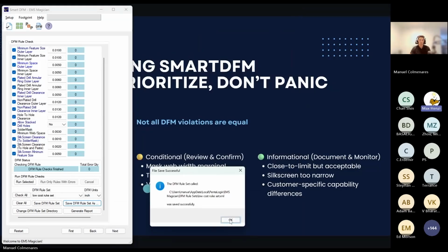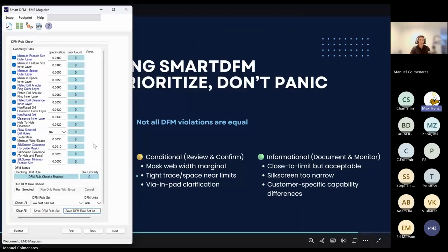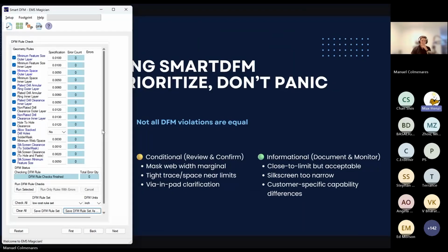And it doesn't have to necessarily align with a particular PCB manufacturer. You can just set up different rule sets for different technology types of boards and then run them through there. And so if you know that, hey, this board shop that I like over here, they can do 3 mil trace and space, but they charge me twice as much as the guys that do the punch and crunch boards. So you can set up the rule sets however you want.